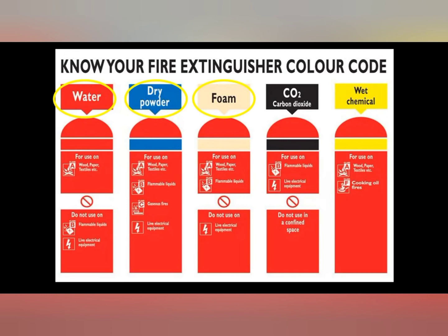Next is the carbon dioxide, which is applicable for class B as well as class C. However, you cannot make use of this in a confined space. And next is the wet chemical fire extinguisher. You can make use of it for both classification A and classification F.